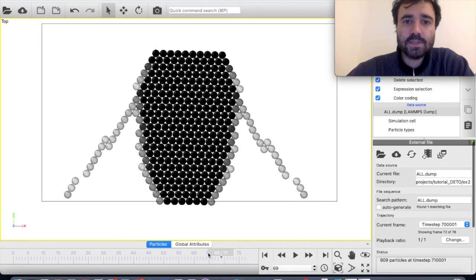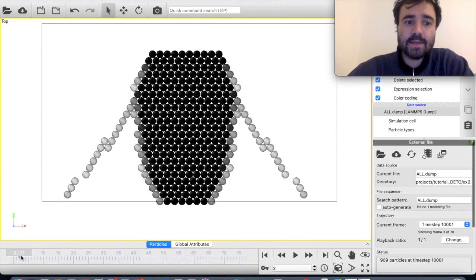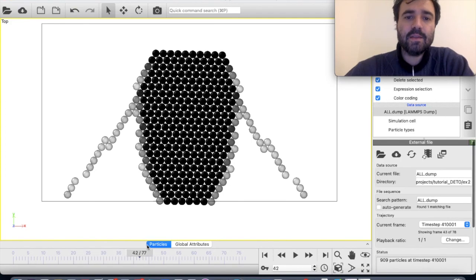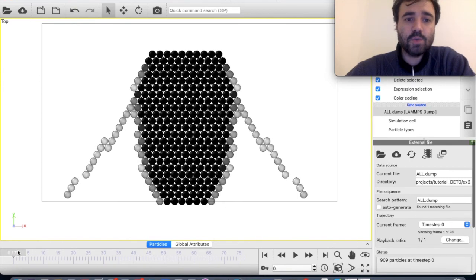It's also tilting because I'm not telling that the top particles have a fixed Y position. If you want it to be pure shear, or simple shear, without any vertical displacement, without any tilting, then you should also add in the input file the vertical position of these top particles. So you see that the system is doing what we want.